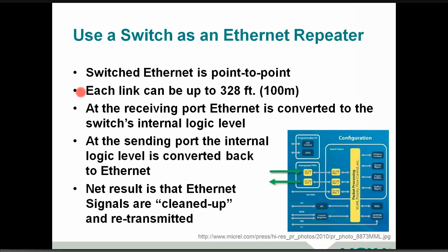And we've got a little bit of a schematic, and I apologize, not everybody's an engineer, but what I wanted to showcase here is that on each link, you have an endpoint of that RJ45 port on the switch, where that signal comes into the switch, gets converted into logic level on the switch itself, and based upon the processing, you'll have a response coming back out on your RJ45 port, where each of those point-to-point links gets cleaned up and passed on to another port.